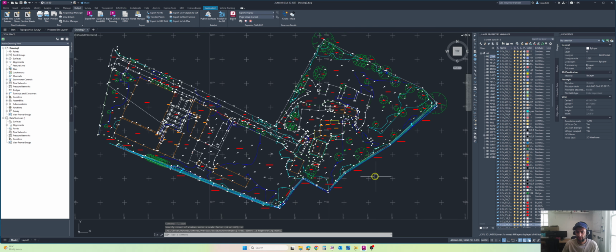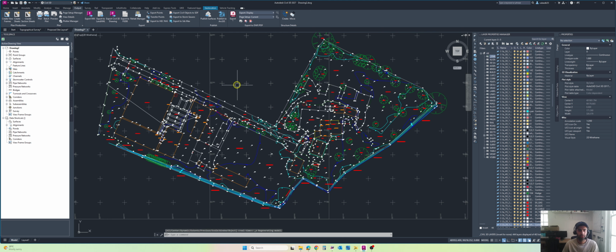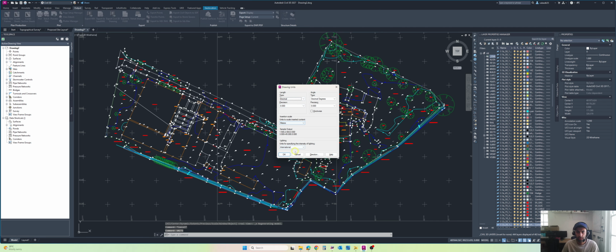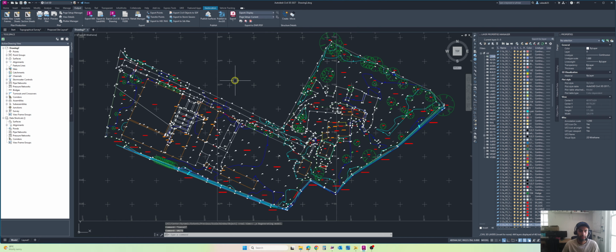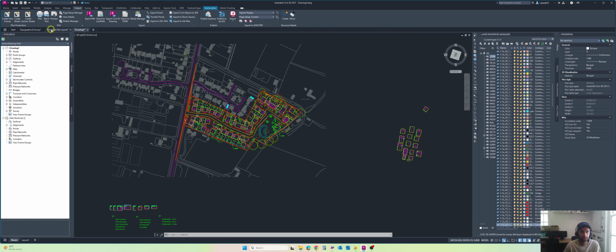So now I can see the coordinate system is right for this drawing, because these coordinates are in 6 digits. Mostly the 6 digits are proper for the UK sites. So I think this is on the proper coordinates. I will also check my units, should be in the meters. In the meters is good. And now what I will do is see my architect's drawing.